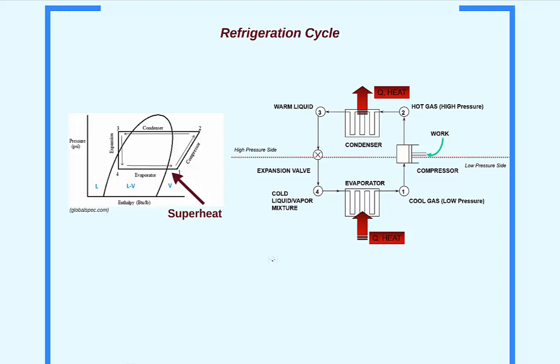The refrigerant cycle, shown on the pressure enthalpy diagram, is scalable. Whether the cooling load is 1 ton or 100 tons, the cycle follows the same shape. The 4 process lines on the pressure enthalpy diagram look the same, but the cooling load is constantly changing. How is it then that the AC unit responds to varying cooling loads? The answer is by modulating the flow of refrigerant into the evaporator.